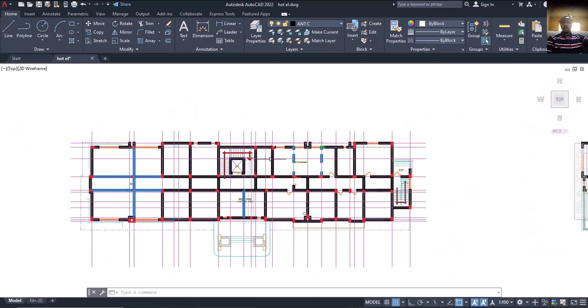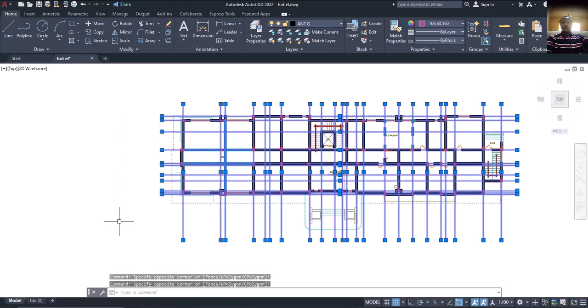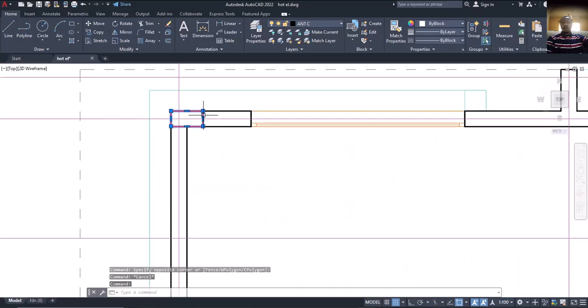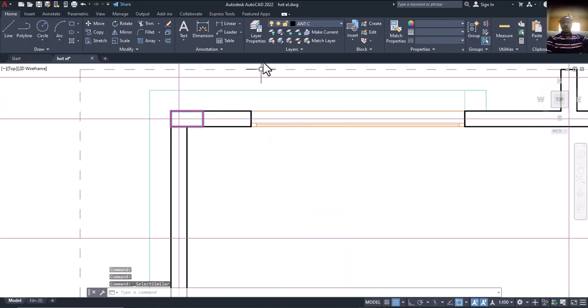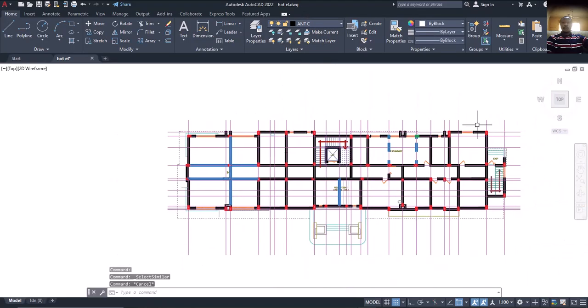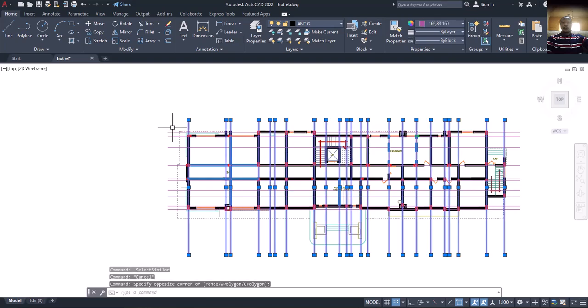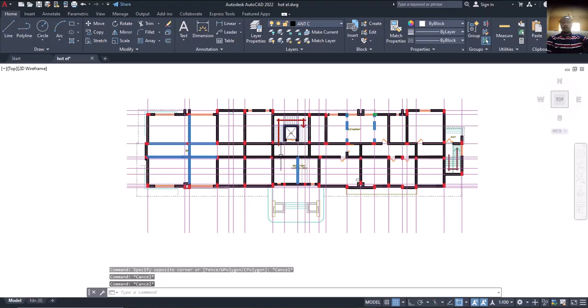So now coming to this place, let's begin to name our axis. Name this axis Anthony Grid. That's the name of your client. Now I'll select the column. Can you see it's already showing me Anthony column? I'll select all of them, and as I click on all of them, it shows the same thing. Which means that during ProtaStructure, this one will be Anthony Grid, and this one Anthony column. Is that okay? So this is how you go about it.